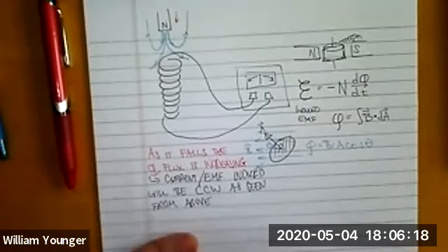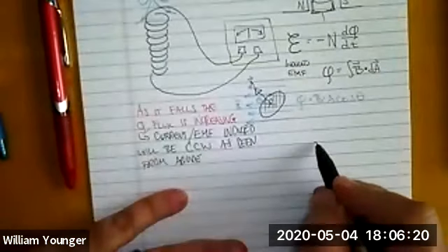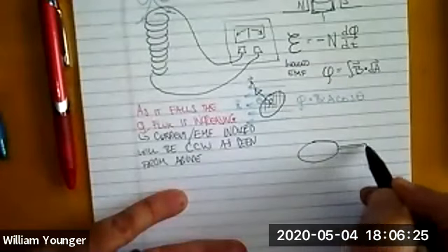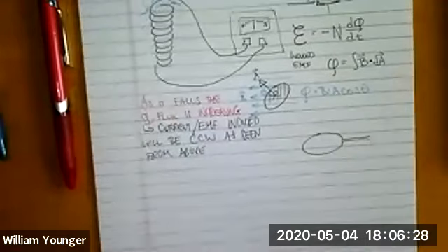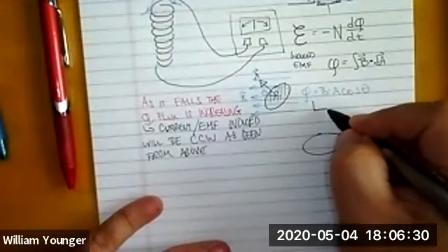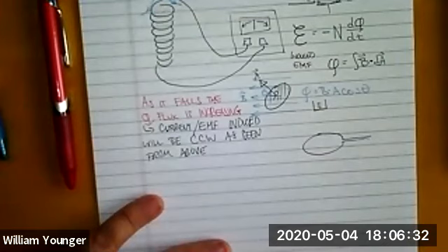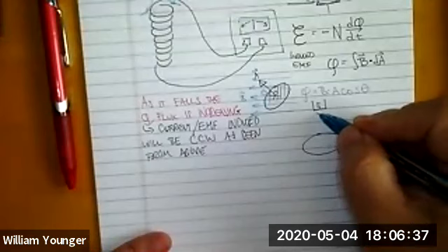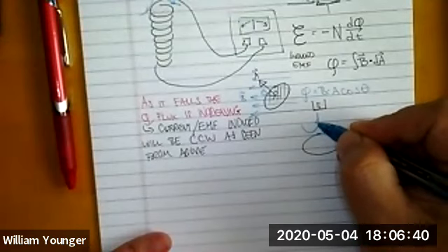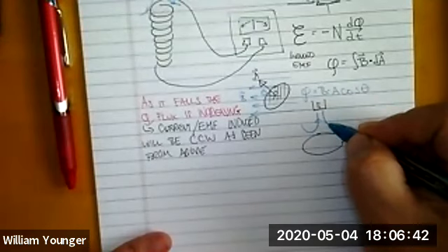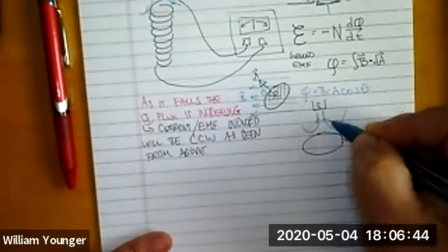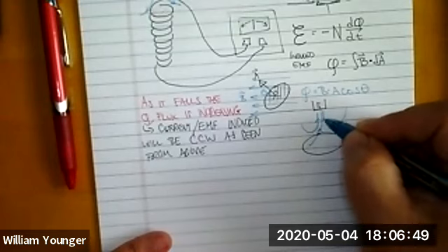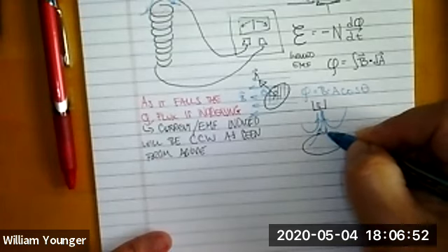Let's imagine, for instance, that a single coil of wire was like this, and then the wire goes off that way, so we can actually measure it to determine whatever's going on. But now let's imagine I put a south end of a magnet down here. That means the magnetic field lines are pointing up when they're strongest. So in other words, you ignore all the stuff on the outside. At the end of the day, really the innermost magnetic field lines are the most important ones because they're closer together and therefore they're the strongest.